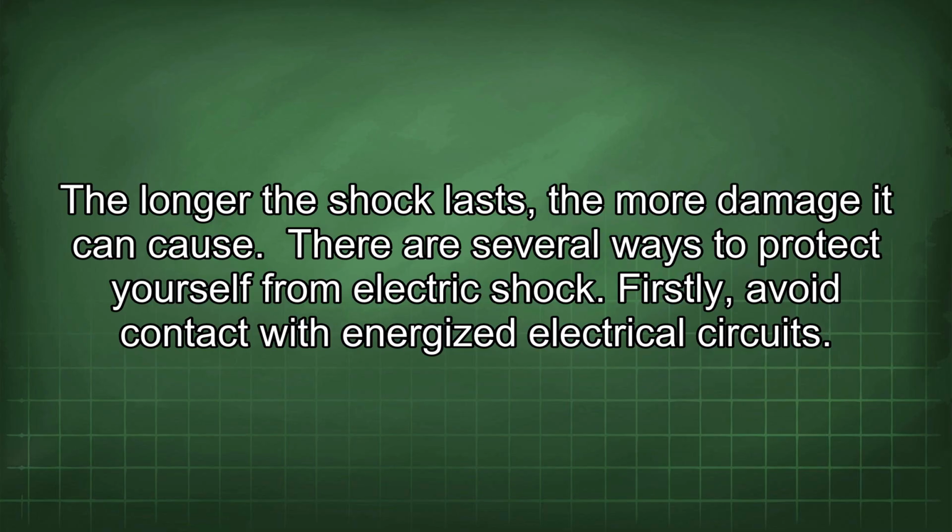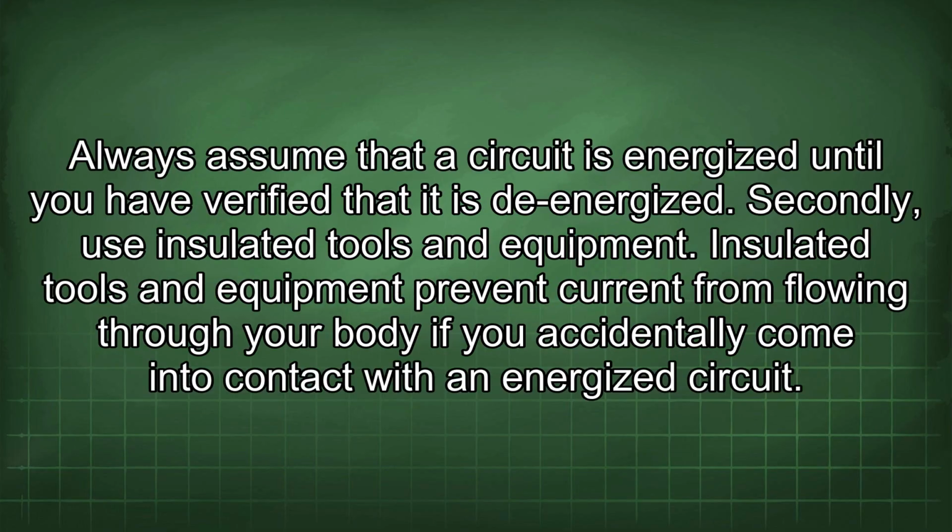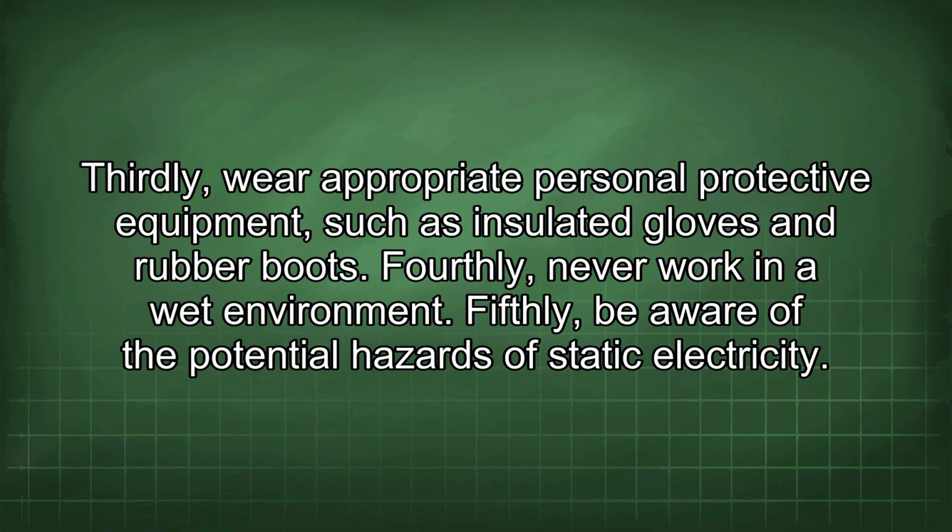There are several ways to protect yourself from electric shock. Firstly, avoid contact with energized electrical circuits. Always assume that a circuit is energized until you have verified that it is de-energized. Secondly, use insulated tools and equipment. Insulated tools and equipment prevent current from flowing through your body if you accidentally come into contact with an energized circuit. Thirdly, wear appropriate personal protective equipment, such as insulated gloves and rubber boots. Fourthly, never work in a wet environment.